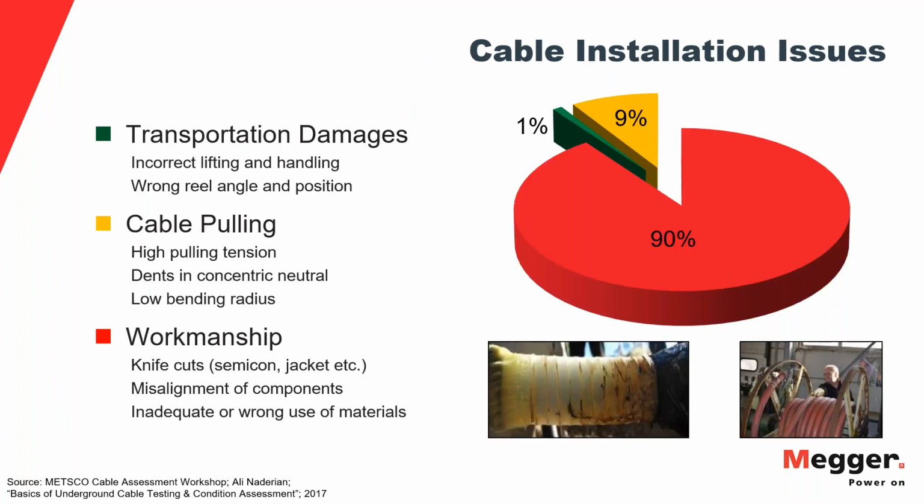Now, why is the partial discharge test so effective and why is everybody so hyped about it? Well, because of this. If you look at the total numbers of cable faults and you allocate them to where it happened, the mechanisms and the parts of the cable, then an overwhelming majority is related to workmanship issues, can be tracked back to workmanship issues.